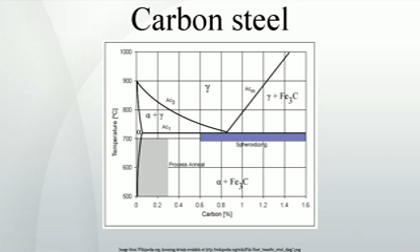Martensite is a form of steel that possesses a supersaturated carbon content in a deformed body-centered cubic, BCC, crystalline structure, properly termed body-centered tetragonal, BCT, with much internal stress. Thus quenched steel is extremely hard but brittle, usually too brittle for practical purposes. These internal stresses cause stress cracks on the surface. Quenched steel is approximately 3 to 4 fold harder than normalized steel, with more carbon.